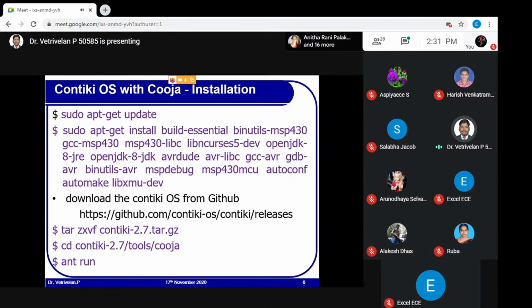If you see here quickly, one is to support IPv6, and to handle the routing we need a routing protocol for IPv6 support, which is RPL, the routing protocol for lossy networks. And the next adaptation is CoAP.